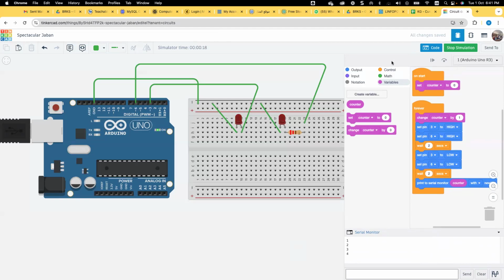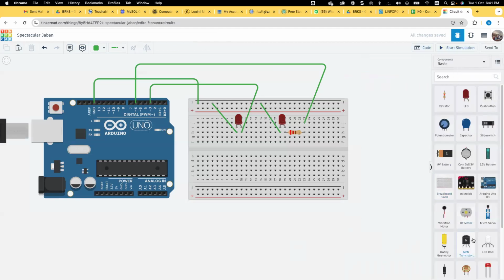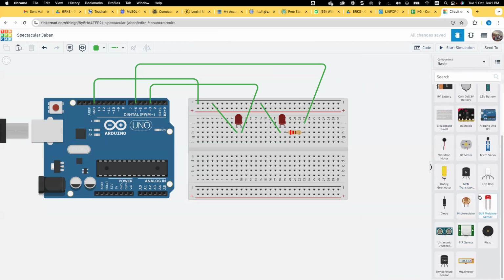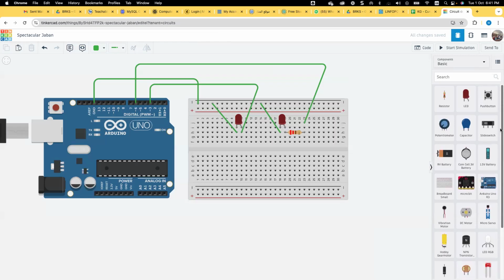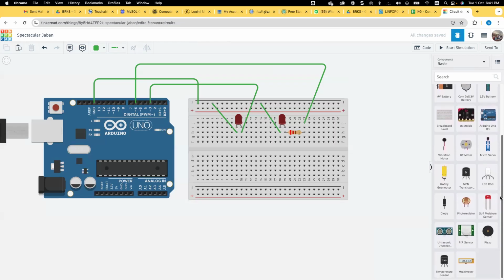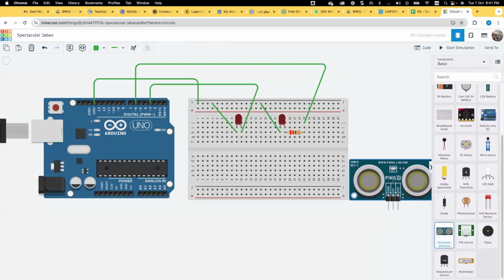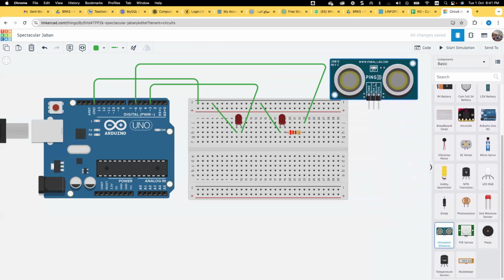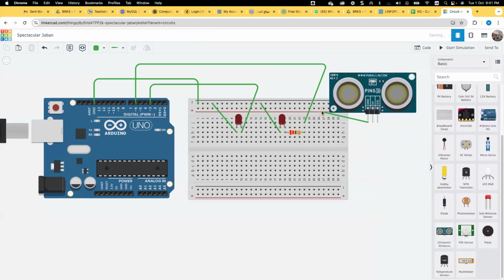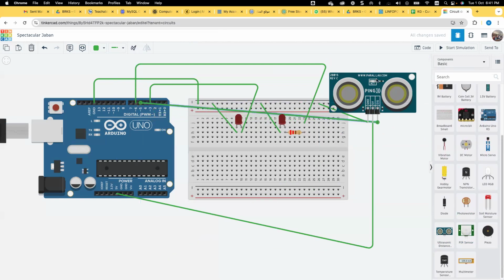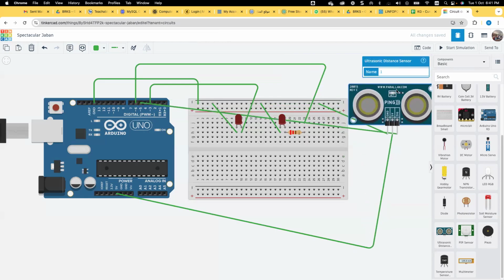And if I want to, let me check if I can add the ultrasonic sensor to measure distance. It's done. So I will go for the ultrasonic sensor. The ground will be connected to the ground, as usual, it's easy. The 5 volt will be connected to the 5 volt, and the signal will be connected to, let's say, 5. Sorry, my circuit is not proper, but it's okay.